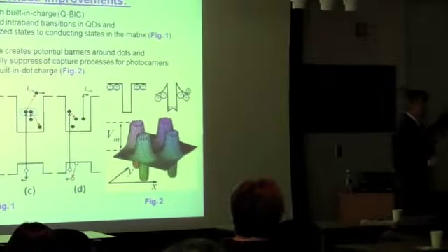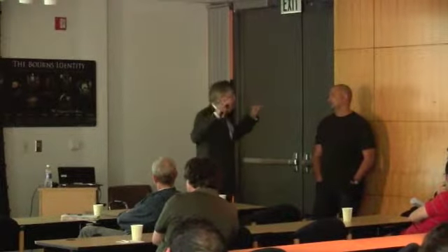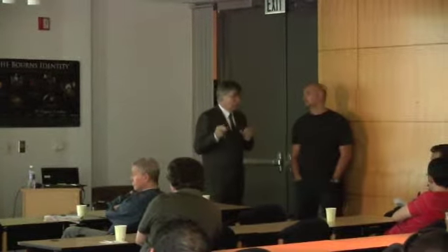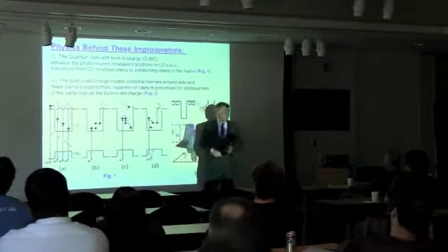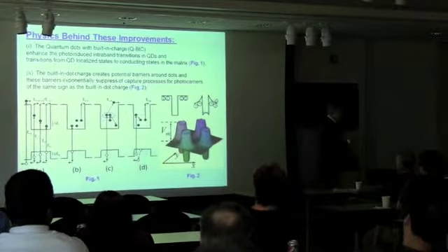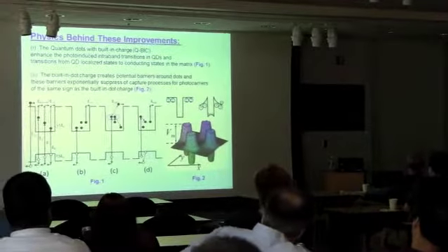So if we charge the dots positively, then this will be like a perfect material for solar cells, because now electron-hole recombination through dots should be, not completely, but largely eliminated, because electrons do not go into the dots at all, because initially there is a barrier. And for holes, you have the dip there. So holes go in, and of course you will have more complicated, indirect recombination. There are some things, but this is a very interesting material.